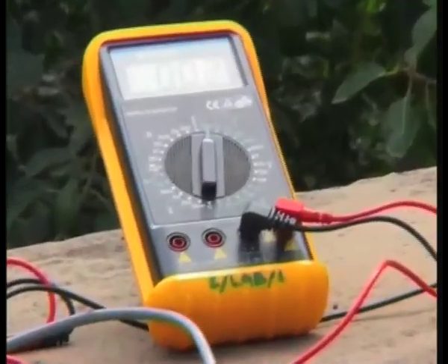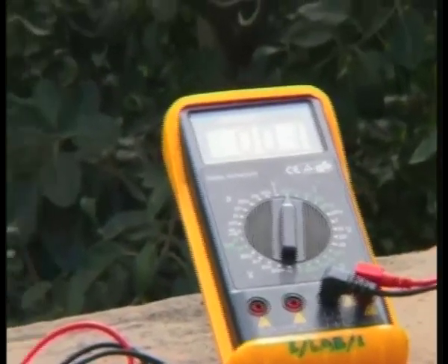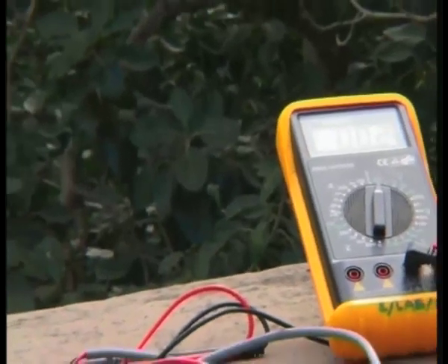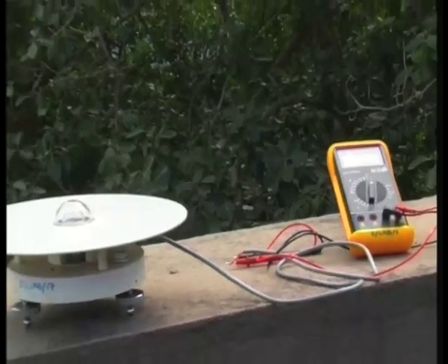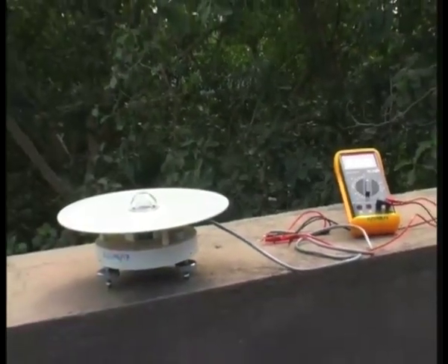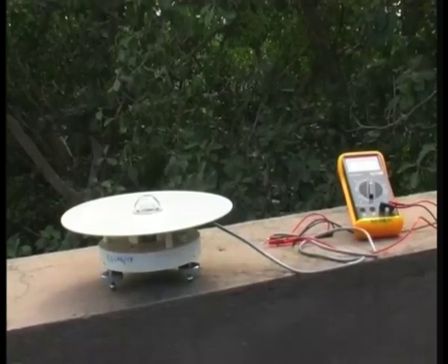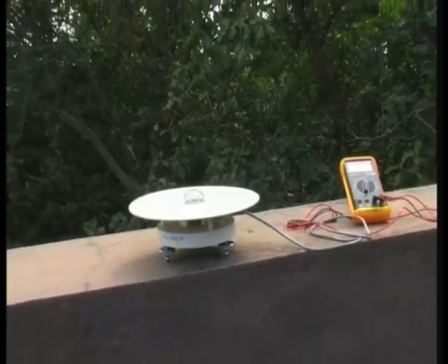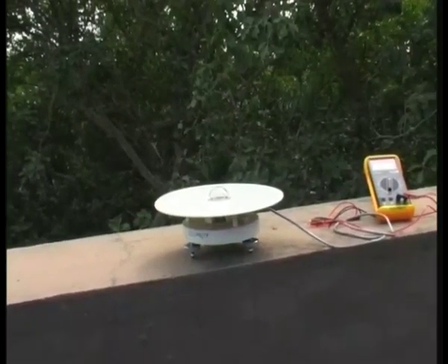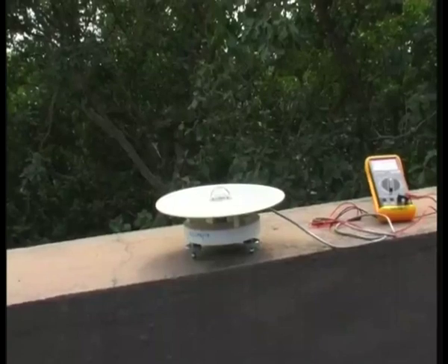So when we try to find out the efficiency of any solar collector, the incident energy has to be found out through the pyranometer reading, and the energy that is gained is to be found out from the temperature difference between the inlet side and the outlet side, and the flow rate. The flow rate can be measured either by a flow meter or simply by collecting the water in some kind of container over a given period of time and then measuring it with a simple measuring cylinder.